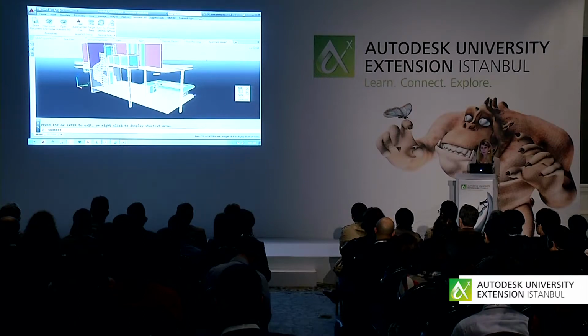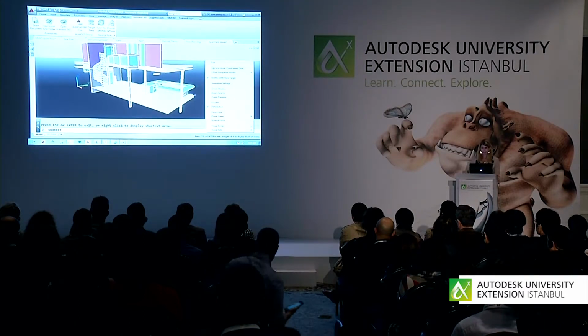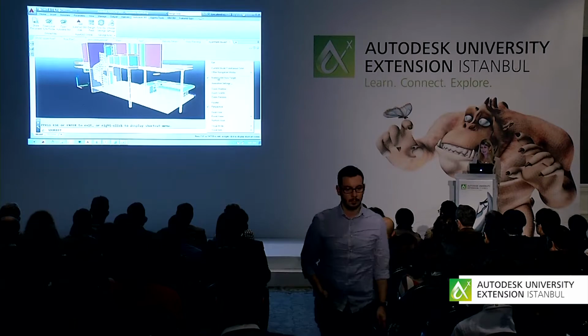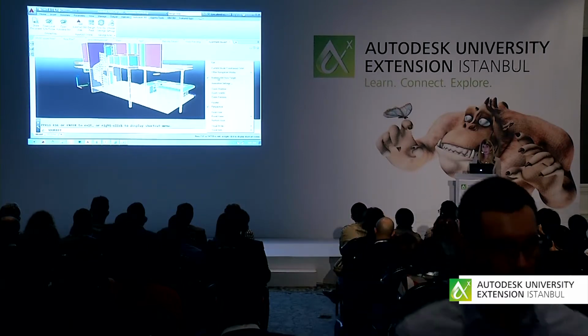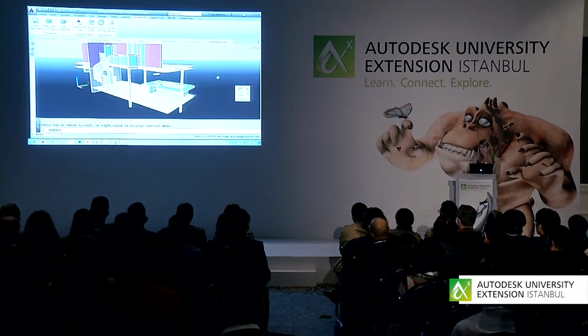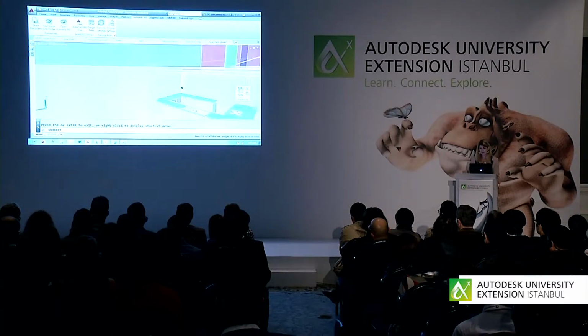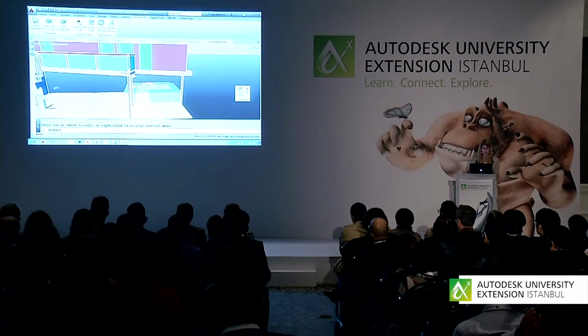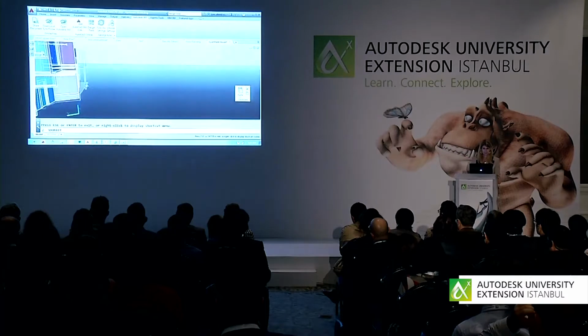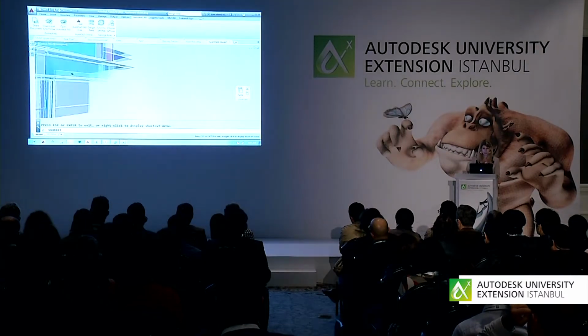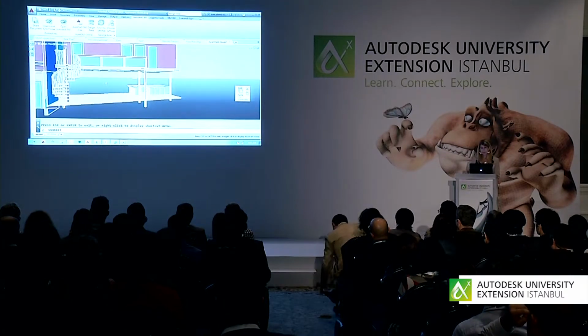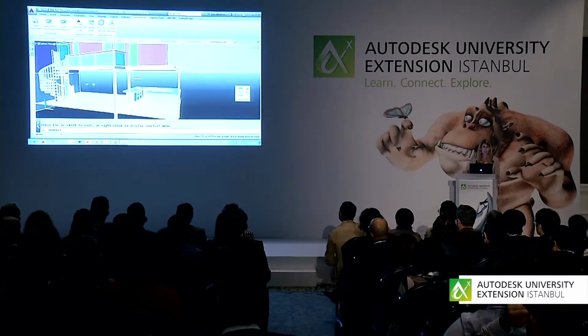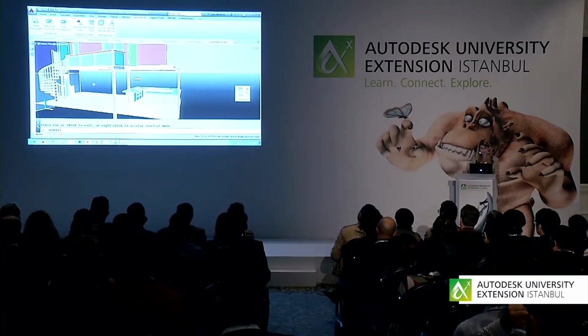So there's a new option in 3D orbit. If you turn off enable orbit auto target, now any place you pick on the screen becomes the center. Maybe I want over here to be the center. Or maybe I want the stairs to be the center. So you have complete control over what ends up being the center of the model when you do a 3D orbit.